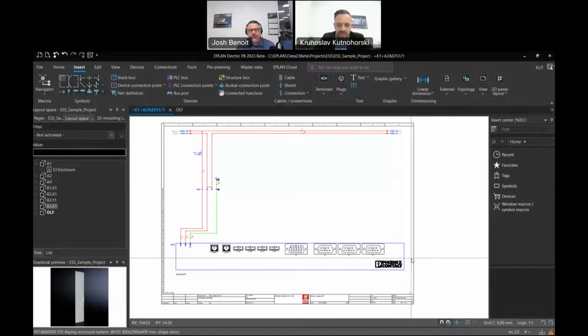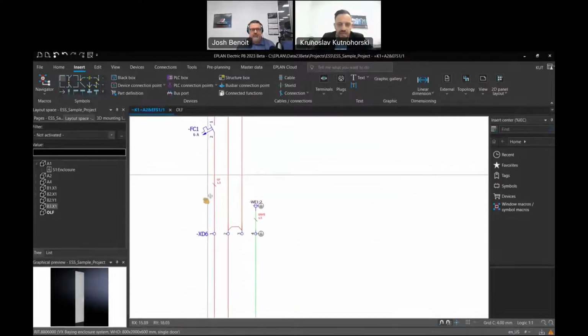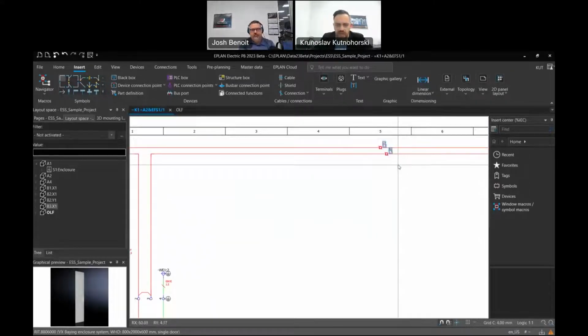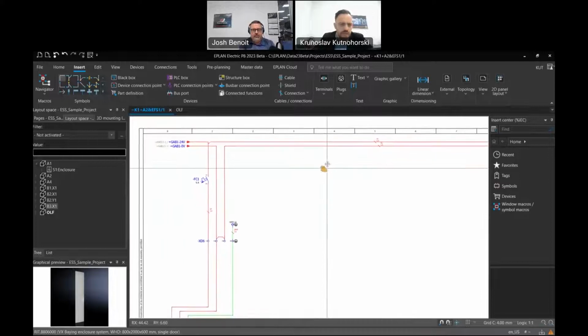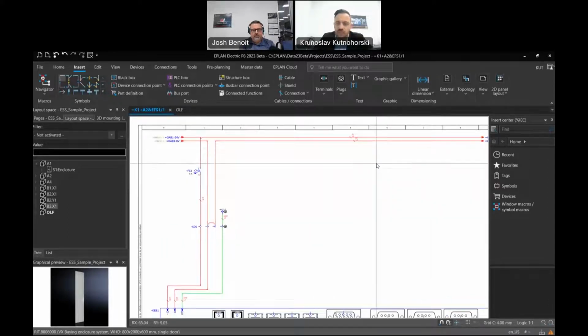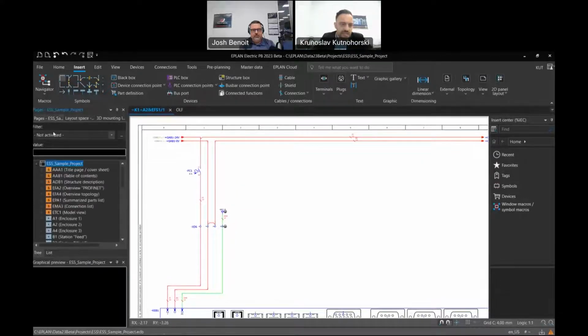In this case, I have just a little power supply page, right? And as you see, I have connections on this page, like connection definition points. Now, whenever I make any type of change and would like to renumber things in EPLAN, it's very easy essentially.